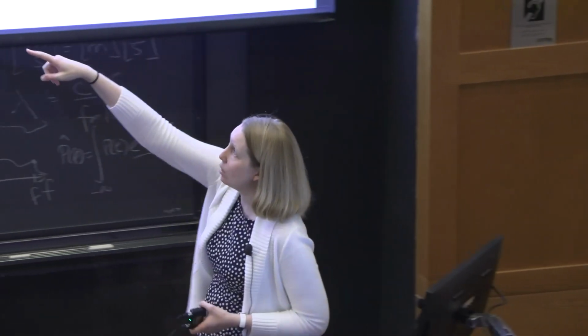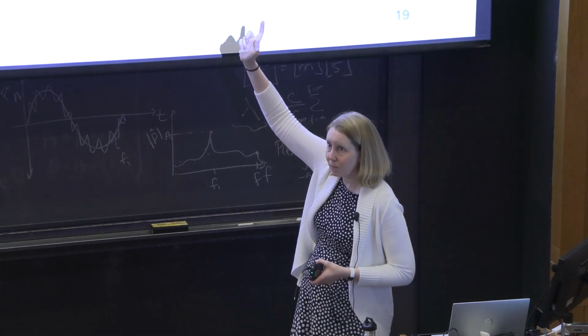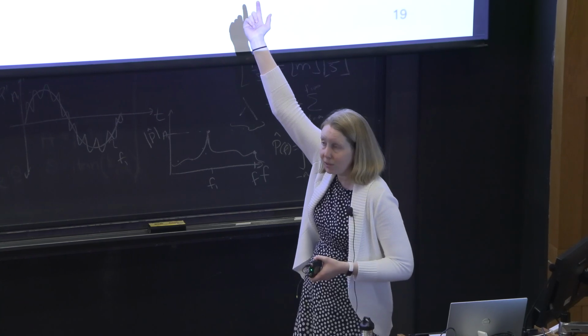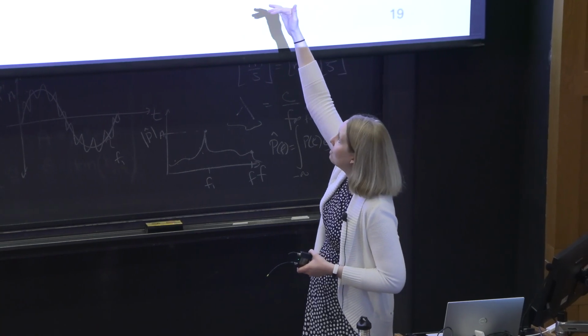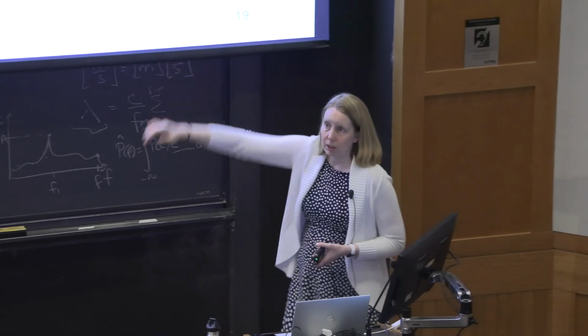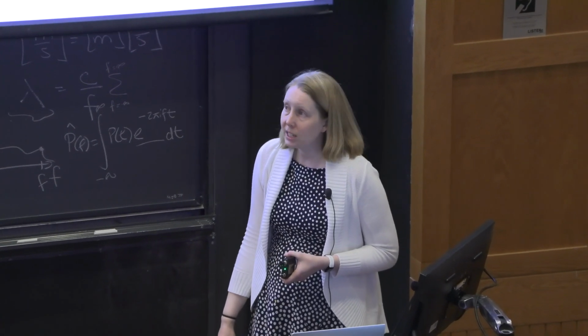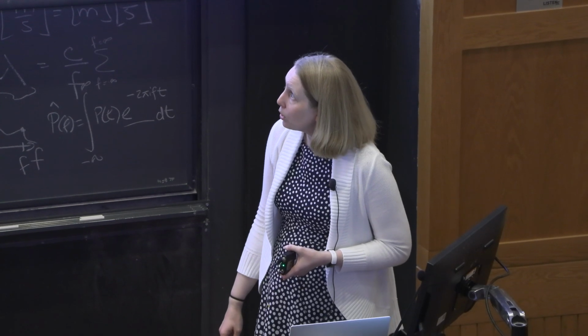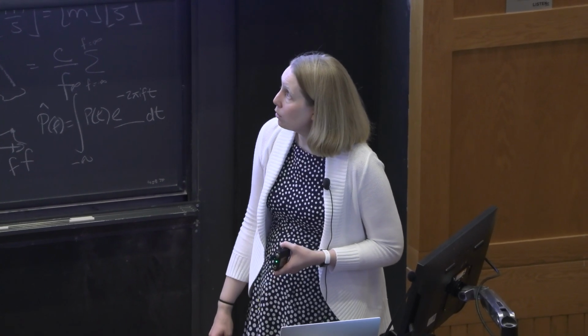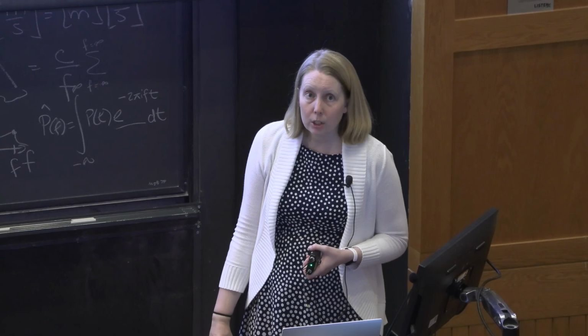And so the speed at which the acoustic oscillation is propagating through the system is still Mach 1 by definition, but the mean flow that would be stabilizing your flame can be whatever. That's fine. And we'll see some examples of some extremely low velocities and some middle-of-the-road velocities as well. Other questions?